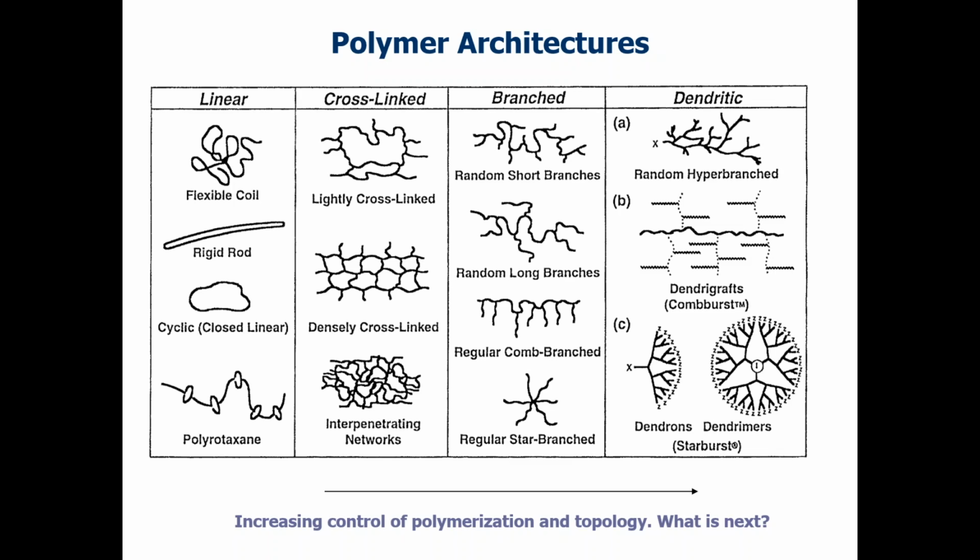of its useful properties. For example, linear polymers are capable, of course, of good crystallizability. Cross-linking results in gels or thermosets. Branching tends to lower the melting point and also cause a decrease in the viscoelastic behavior. Dendrimers and hyperbranched systems are interesting because they have high molecular weight but flow very well, or have low viscosity.